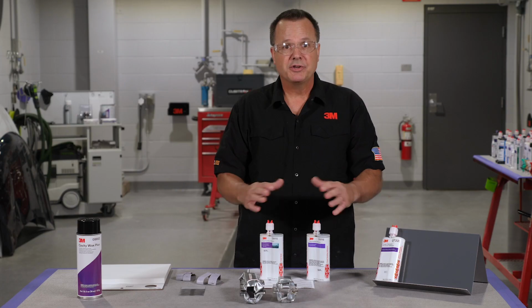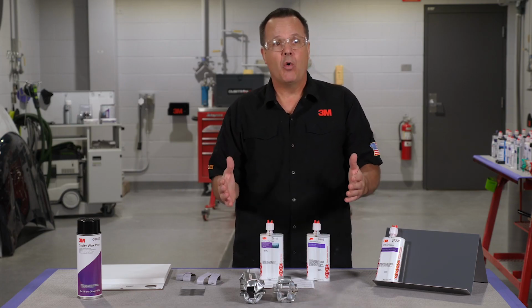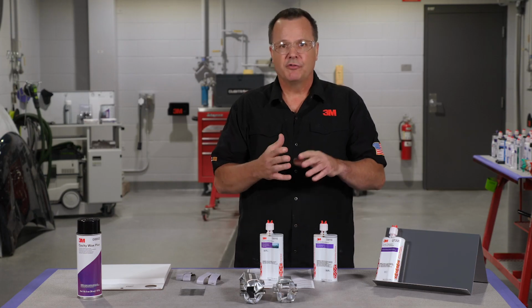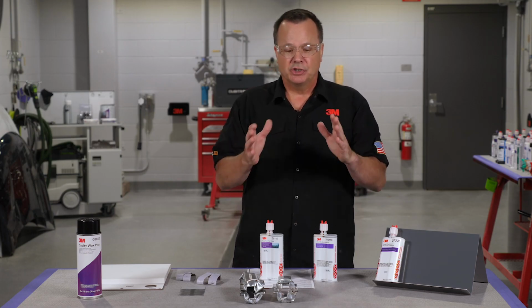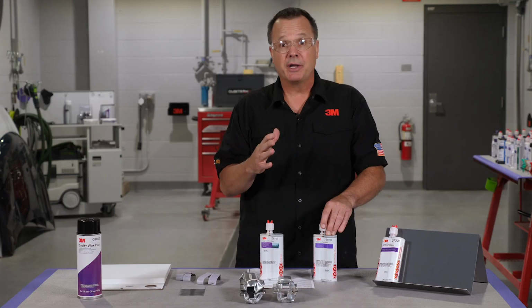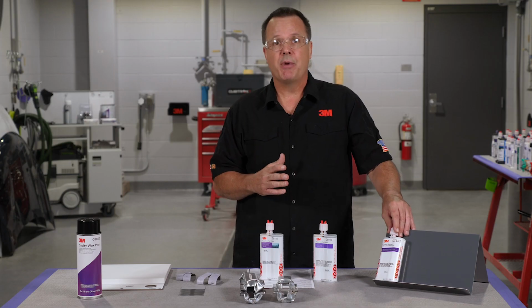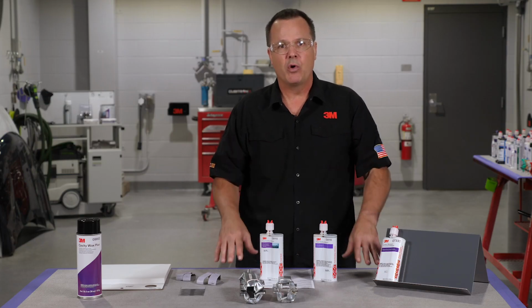So now the other part to that question is, how do I know when to use one or the other? And obviously we're going to follow OEM recommendations, but I can tell you that for the 8116, Chrysler wants it used for all their bonding operations. General Motors also specifies 8116, but only for the door skin bonding operations. All other bonding operations for General Motors, they are now recommending the structural adhesive. So those are the differences, and those are where you would use each product. But again, it all comes back to getting into those procedures and following what the OEM says.